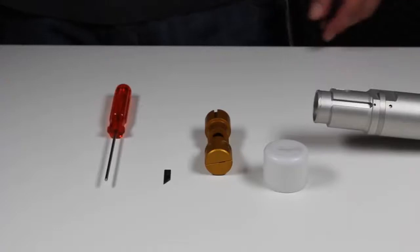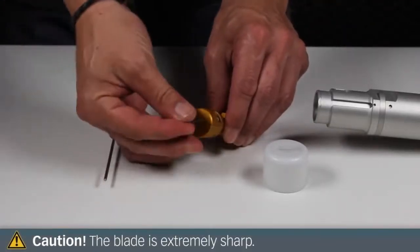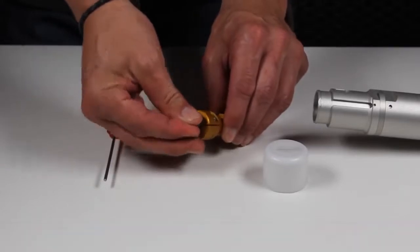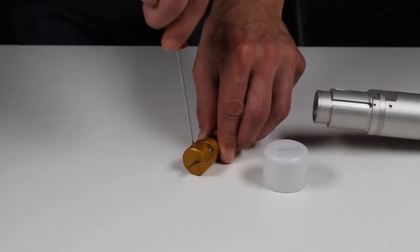We are now inserting the blade. Insert the blade up to the cutting edge in the blade holder. Fix the blade in place in the blade holder using 2 Allen screws.